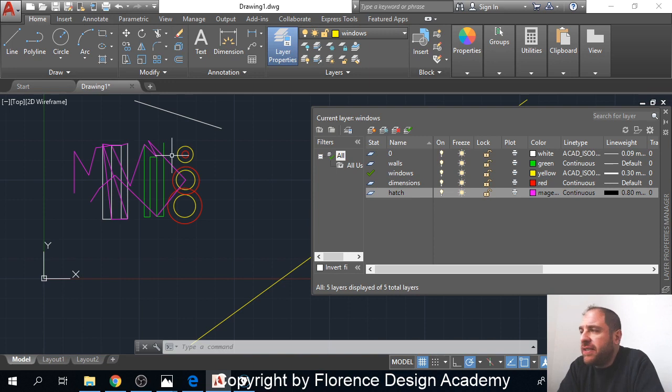And this is simply because by default, and only by default, line weight will be visible only when you print. And this can be something pretty annoying because you want to be sure that all of your line weights are correctly working. So, only for this reason, you need to use a button that is in this lower area of the screen.